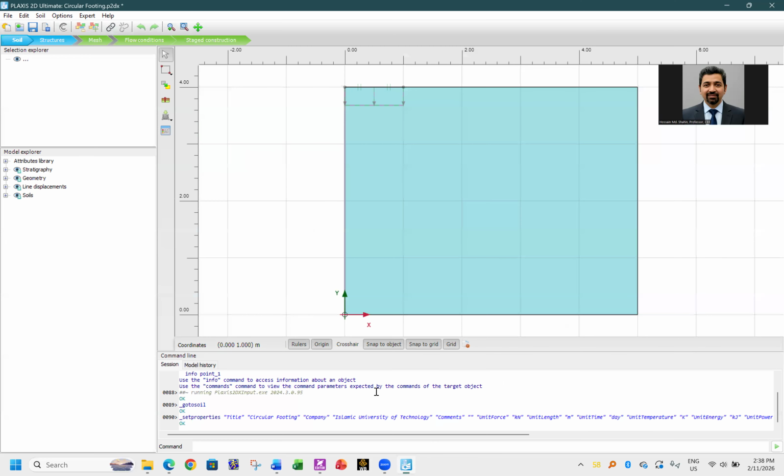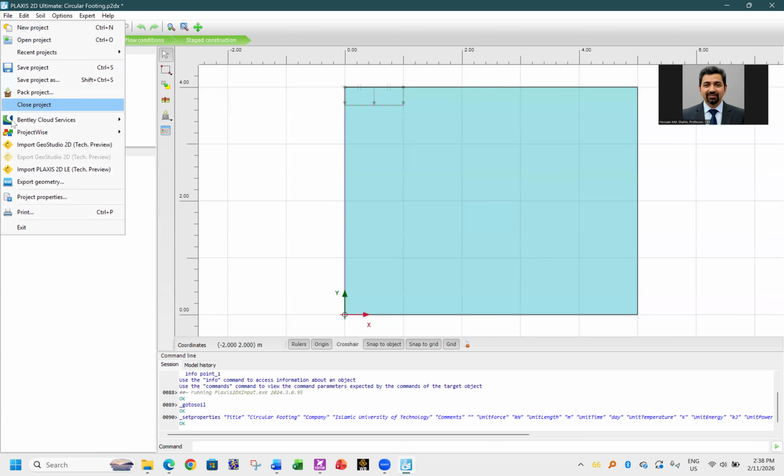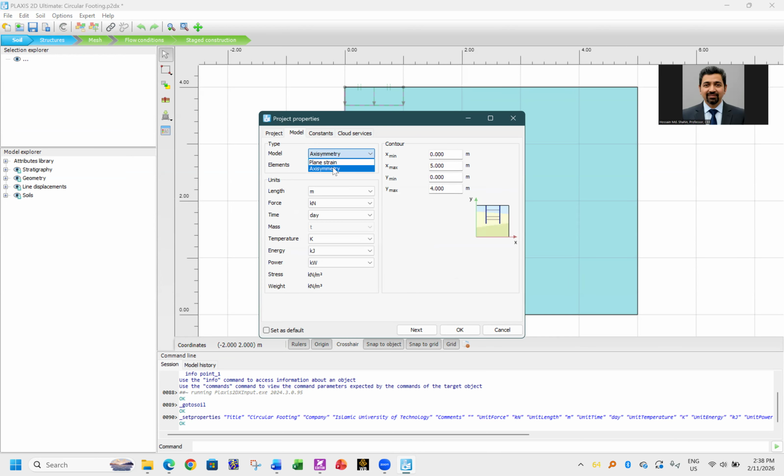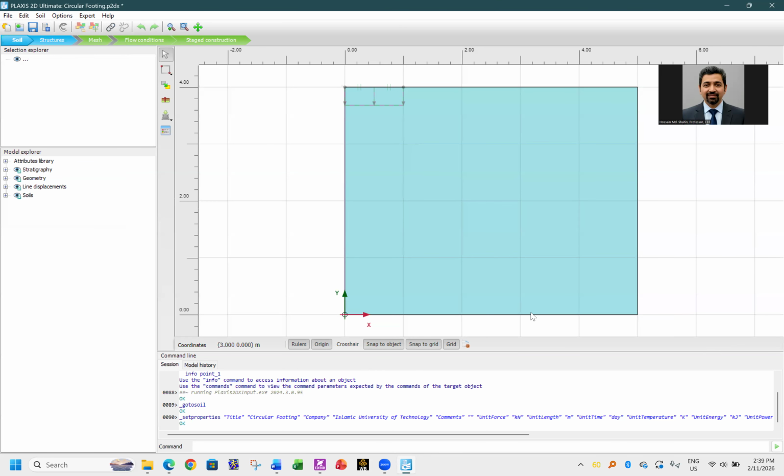I have my own program. You can check here. Model, axisymmetric, no, only plane strain and, sorry, plane strain and axisymmetric condition. Whenever you do 2D analysis, you must consider whether your condition is plane strain or plane stress. Axisymmetric actually is 3D, in fact, but you can do it by 2D analysis. The B matrix is 4 by 4 like this.